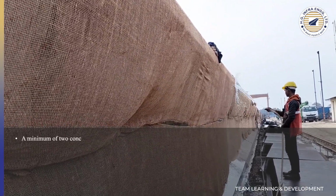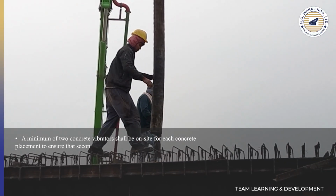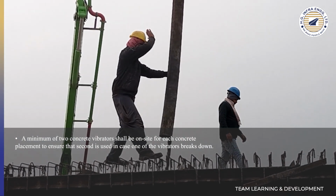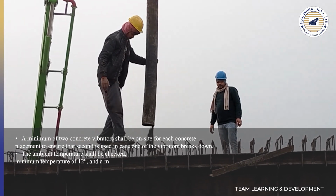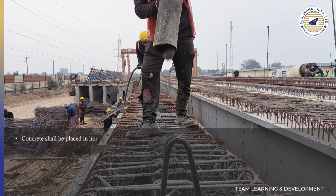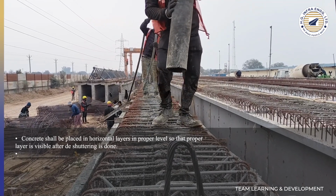First point, a minimum of 2 concrete vibrators shall be on site for each concrete placement to ensure that second is used in case one of the vibrators breaks down. The ambient temperature shall be minimum 12 degrees and maximum of 35 degrees. Concrete shall be placed in horizontal layers in proper level so that proper layer is visible after de-shuttering is done.